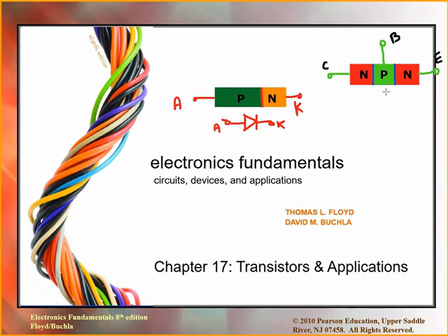And we have already seen the concept of how the diode works. So a diode works in one direction only, and in order to operate a diode, we have to bias it. How to bias? Either it should be in forward bias or it should be in reverse bias. So there is a condition for that. And what is the condition? Anode should be greater than cathode, or we can say P type should have voltage greater than the N type, then it will be in forward bias, right? This is the concept. This is just a basic which I explained to you.